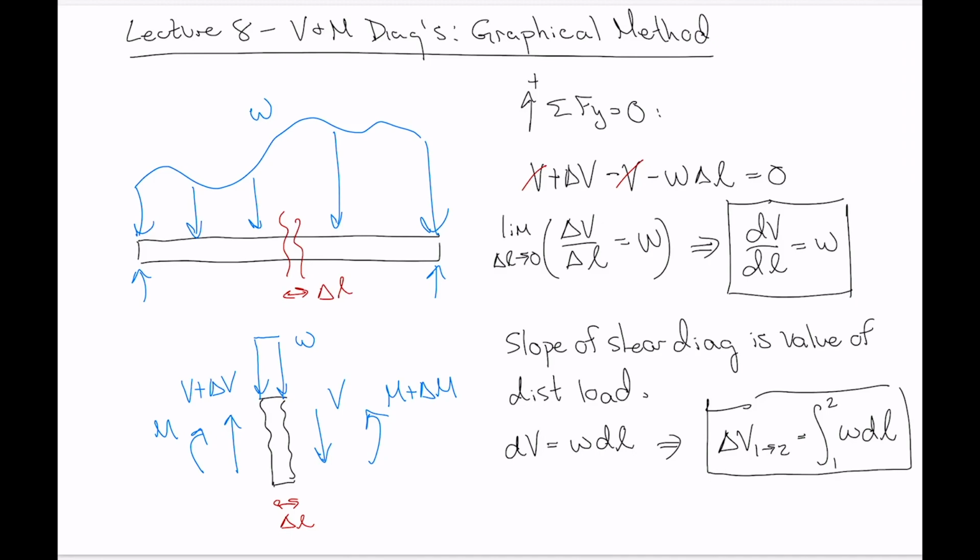Okay, so that says that the change in shear between any 2 points is the integral of the distributed load between those same 2 points. Okay, so change in shear is area below distributed load. All right, so there's our relationship between distributed load and the shear diagram.